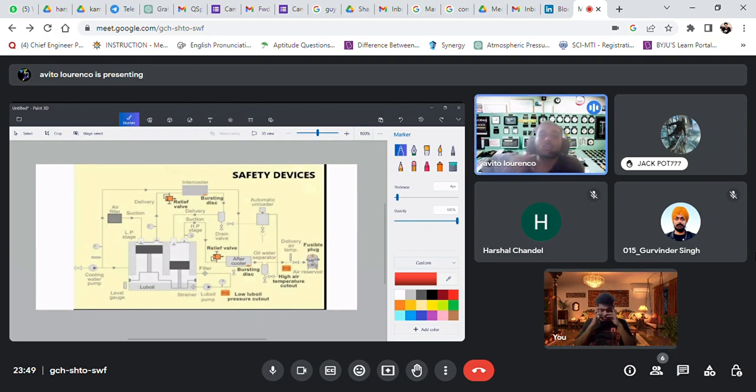So we're only calling the high temperature water the water which is coming from the main engine jacket. That water is super high temperature. So I use my fresh water, which is separate from that, to first heat up this low temperature water, which is the dark blue color.